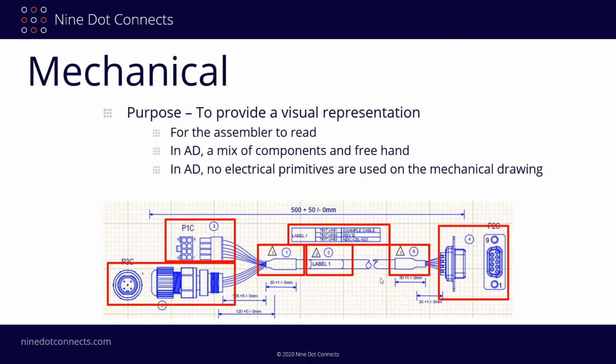And as I said, the biggest problem we have with cabling is that once you create something in the symbol and put it on the schematic, it's too rigid. I can't move it around. You're going to even see some limitations and issues with the label and the heat shrink as well. There are some tricks that we employ to do these, but when it comes to the cable, it's just too difficult to represent it from a mechanical point of view. So we only treat it as electrical.